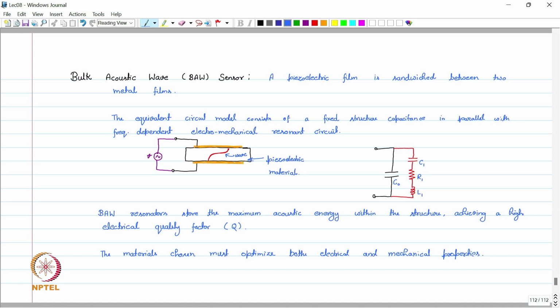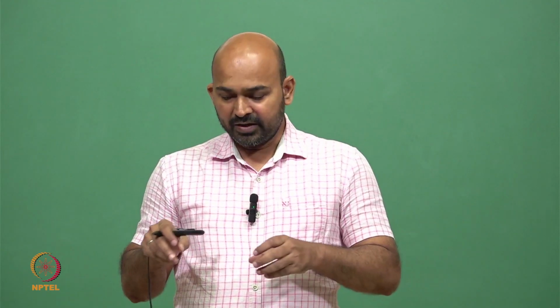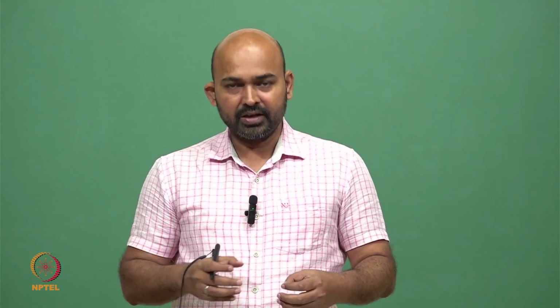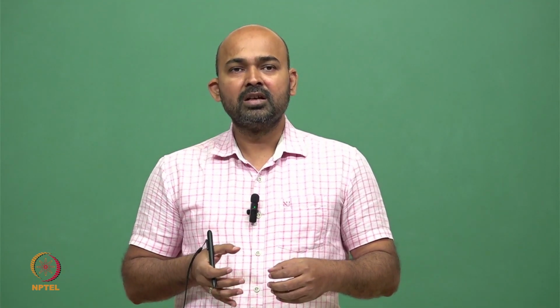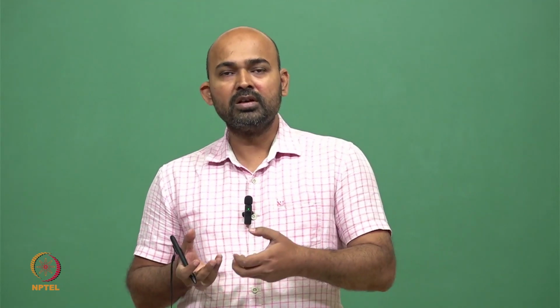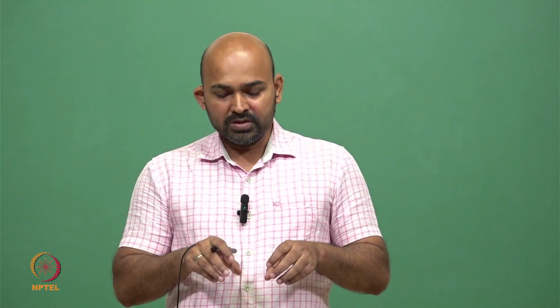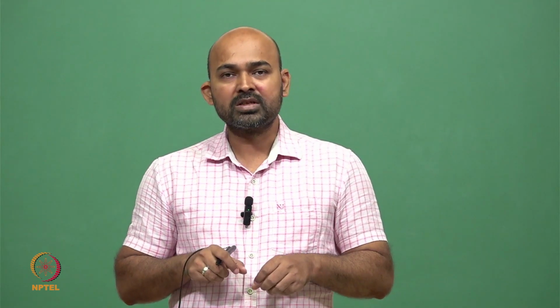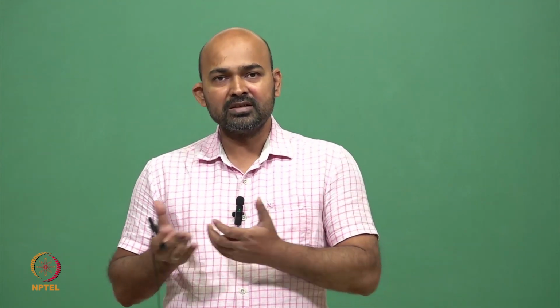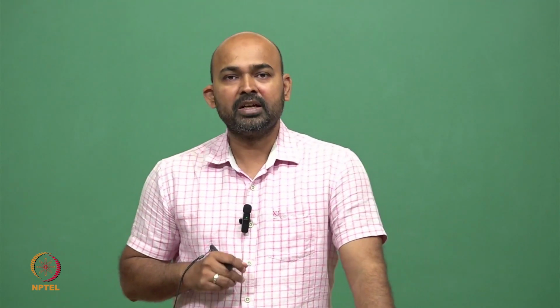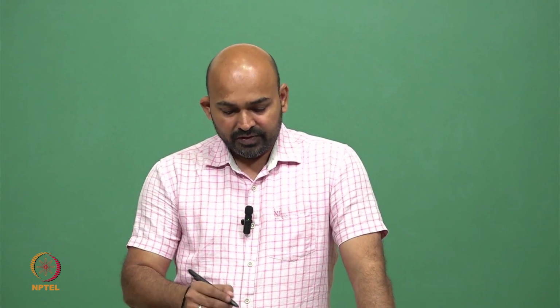So we have this BAW resonator, in fact, and this resonant circuit, whenever we have a resonant circuit, we have an associated quality factor with this, how much energy is stored within the structure, that defines how much the quality factor is. And the material we use for fabrication of these BAW sensors must be carefully chosen, because it involves electrical as well as the mechanical properties of the material. So we have a quality factor associated with these devices.